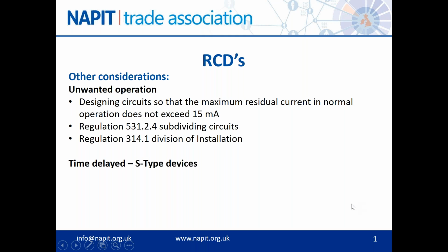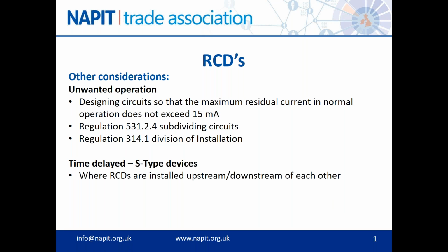We can also employ time delay RCDs. The S-type RCD, the selective type RCD, is used upstream, downstream of each other, and basically speaking, it will look after things for discrimination. Talk about discrimination in a minute. Please remember, any RCD above 30 milliamps, and especially selective types, are not additional protection RCDs. They will not protect life. They will protect against fire. They will protect circuits, but they will not protect life.